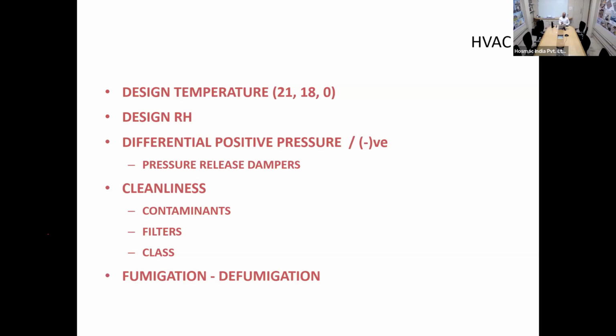So, which is why you have something called a pressure differential manometer. You have that contraption mounted outside the operating room, which will tell you that your room is actually being maintained at positive pressure, or it has kind of been compromised and the pressure is falling and it's become neutral or negative. So that monitoring is as important as planning and executing for positive pressure.